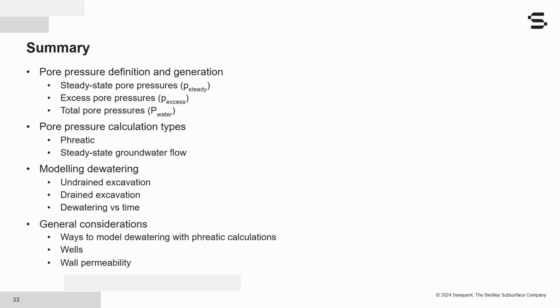Boris asks, would you use the fully coupled flow analysis for excavation of shoring walls or shafts? Personally, I would. I love fully coupled flow deformation because you have the ability to model, like we said, the simultaneous deformation and changes in deformation and pore pressure. It takes a bit more time, depending on, of course, the complexity of your model. But maybe it's better if you started with a simpler phreatic or steady state, and then later on in your design, maybe you want to also perform a fully coupled to see how much difference you get, because it's usually a calculation type that takes more time to complete.